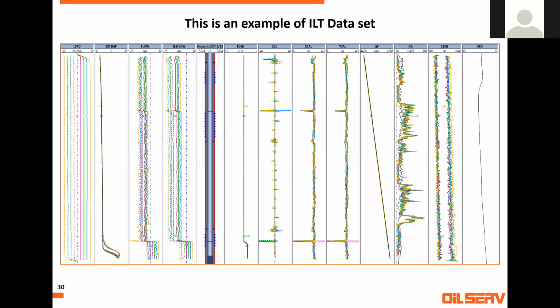Maybe I have to use something similar to that completion, like a direct perforation. In this type of completion, there is a casing that has been perforated, then they run a tubing inside this casing, with small controllable windows, so they can control the injection. What the client wants to see is which of these small windows is taking injection. Okay, this one, 1, 2.